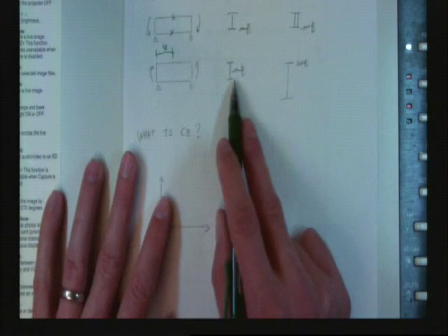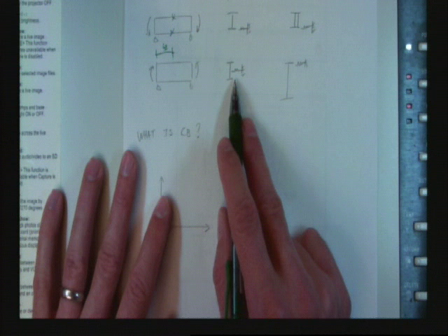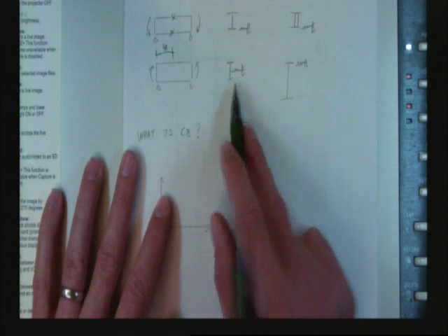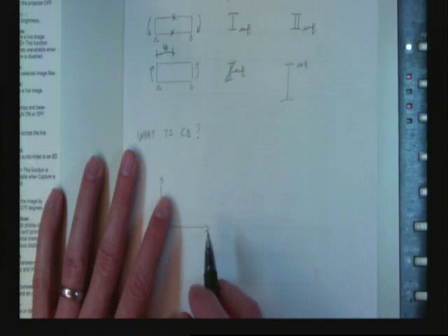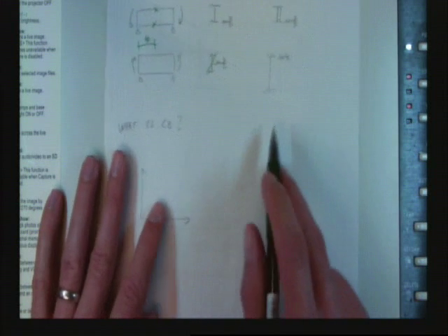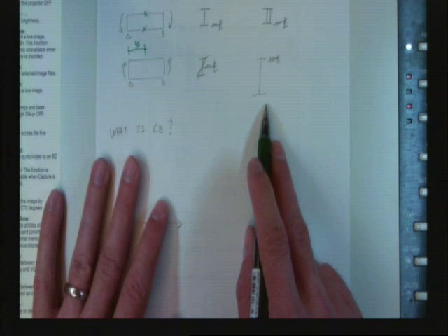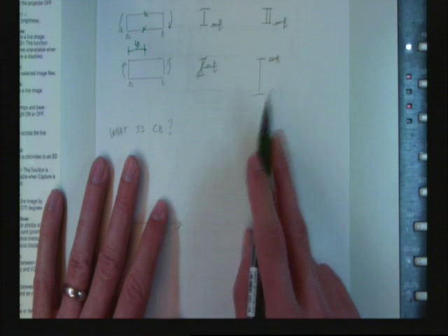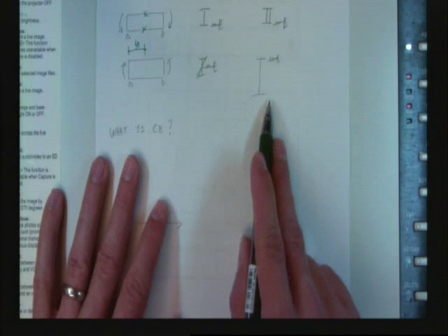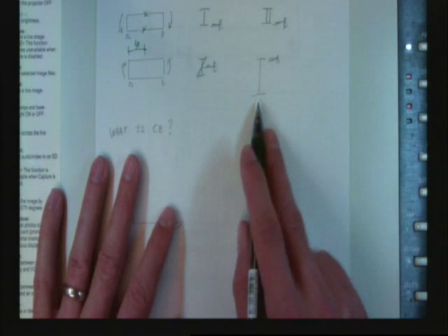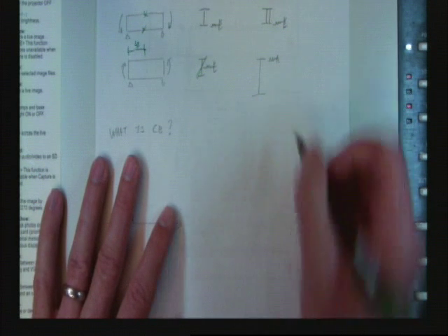Okay, so now how about if I do this? No. It's just actually going to rotate around the brace, isn't it? Okay, so how about this? That's a deep one. The brace at the top. Not good enough, is it? How do I brace this? I could add a stiffener. What else could I do? Could brace the bottom.